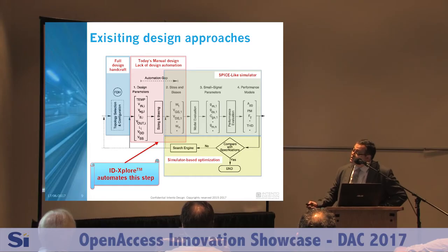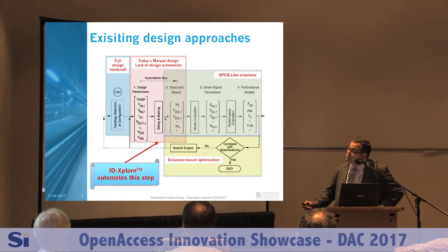So in Intento Design, we were able to develop a constraint-driven design methodology that can deduce vector 2 directly out from vector 1. The designer can select the topology, select some parameters on this topology to control, and these two pieces of information are enough to do this mapping. So we can automate the whole flow from 1 to 2, and we are much, much faster. The particularity of this vector is also that most of the time it pushes the optimizer in the feasible region.